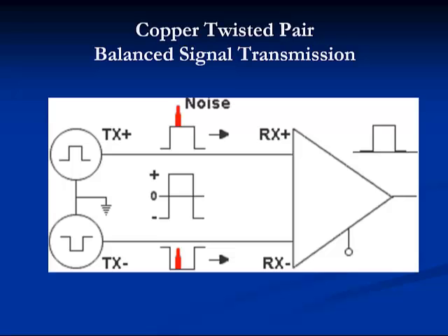Resistance unbalance occurs when the dimensions of the two conductors of the pair are not identical. Mismatched conductors, poorly manufactured conductors, or one conductor that got stretched during installation will result in resistance unbalance.